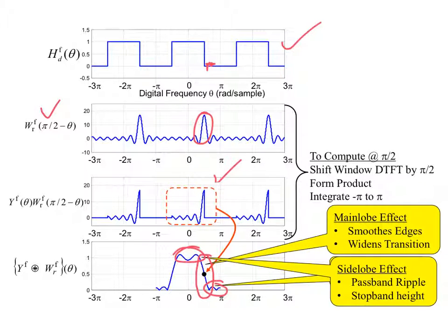We pick a window to control the pass band ripple and the stop band ripple through the side lobes of the window's kernel, and then we choose the length of the filter to get the desired transition band. That's how this design approach works. But again, even with the window, this is still not the preferred design approach, but it's better, and we're getting to something that's conceivably workable.